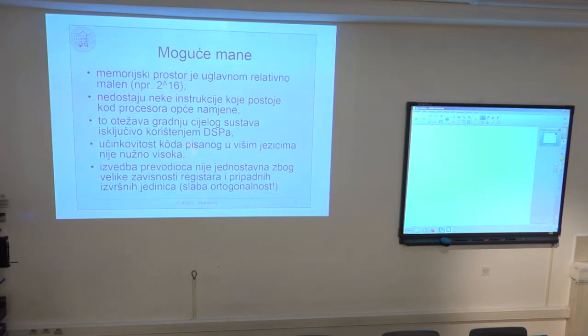Because if you have, for example, some operating system that is written in higher level languages like C, then compilation of this operating system into the assembly instructions on this kind of architecture, DSP architecture, is not very efficient, since it lacks some instructions that are very important to have the efficient implementation of an operating system. But again, it has instructions that are tailored to do the mathematical operations in a very efficient manner.